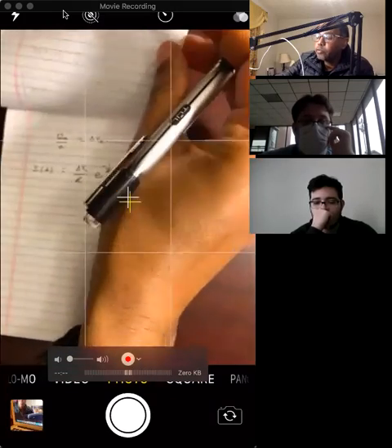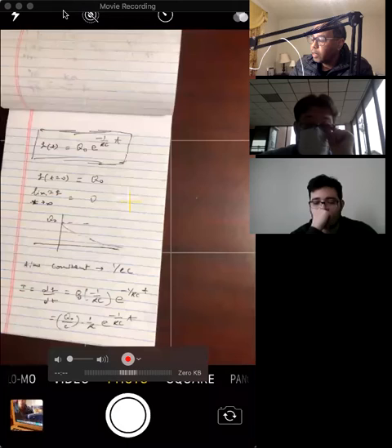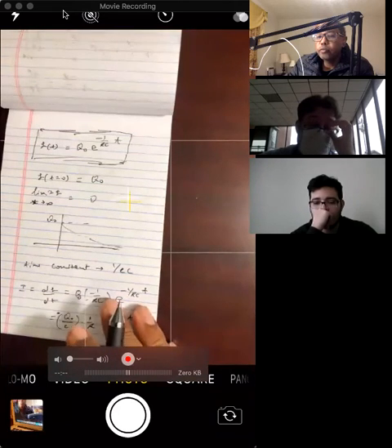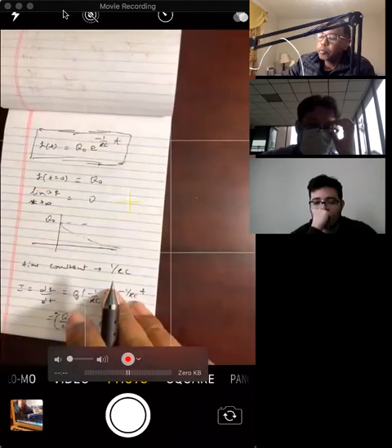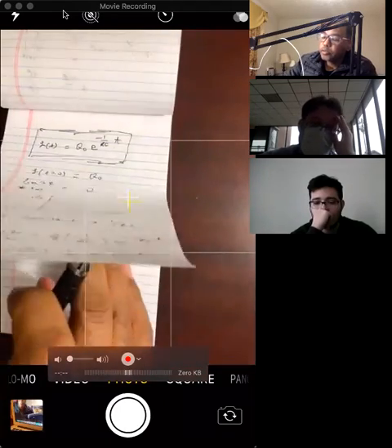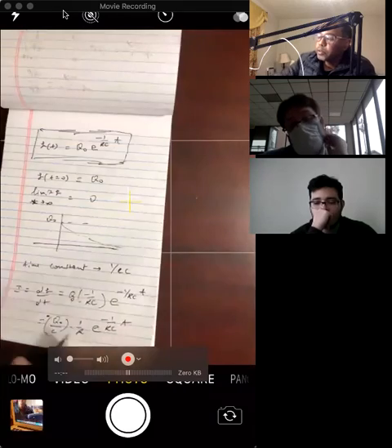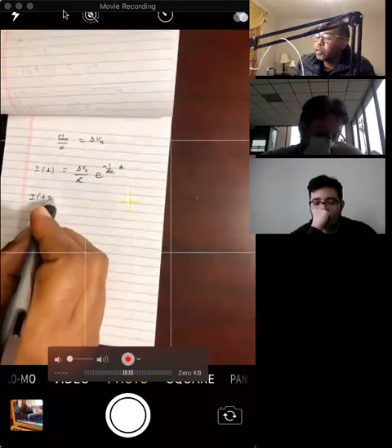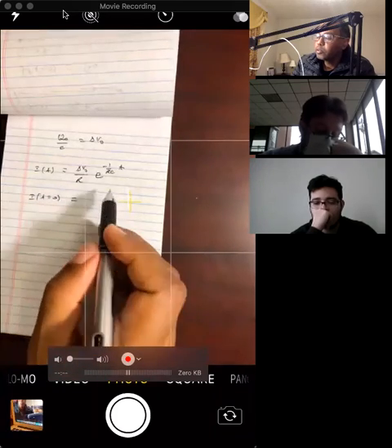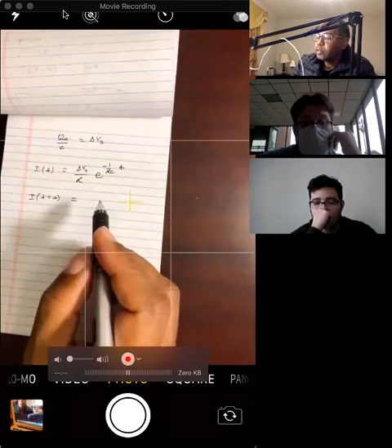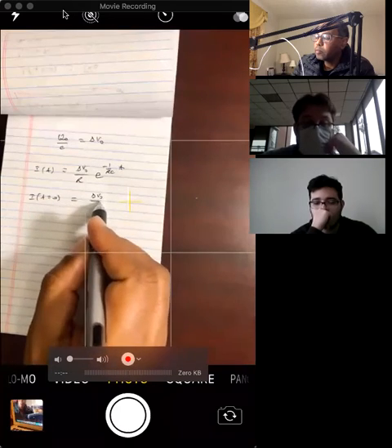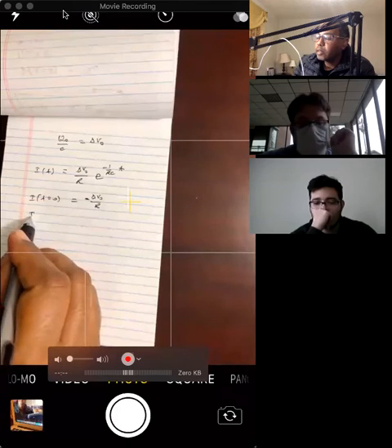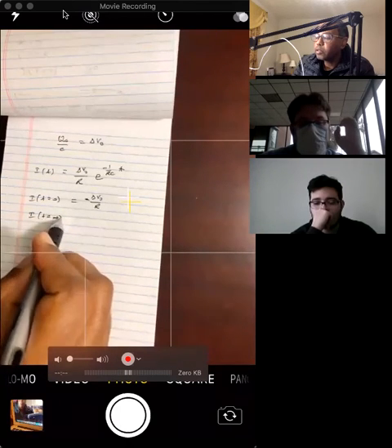But we have a negative over here. The negative means it's a derivative, so the derivative is decreasing. That's where the negative comes from, because the charge is decreasing, the derivative is negative. So I at t equals 0, you put 0 over here, you get delta V naught over R. Actually, negative delta V naught over R. And current at t equals infinity would be 0.